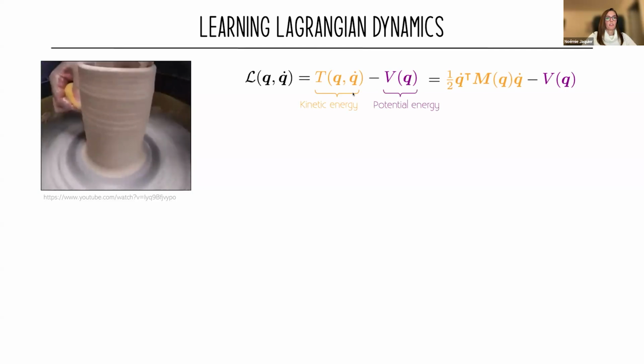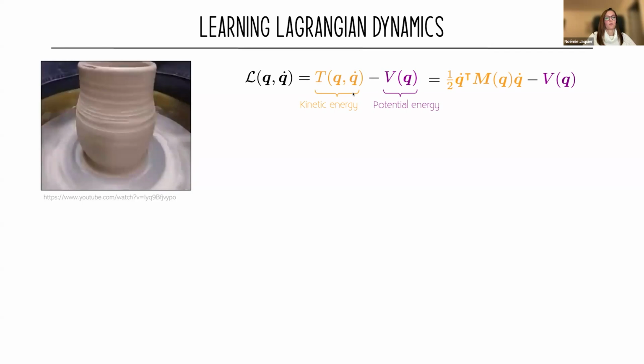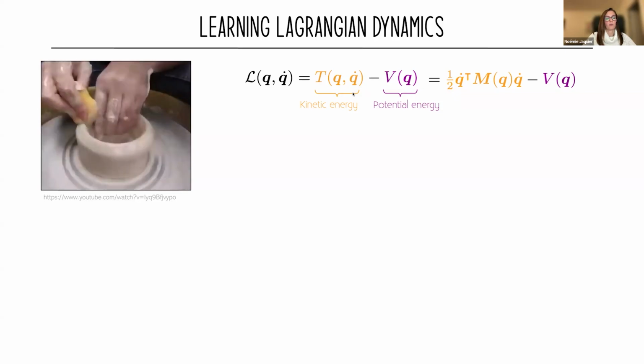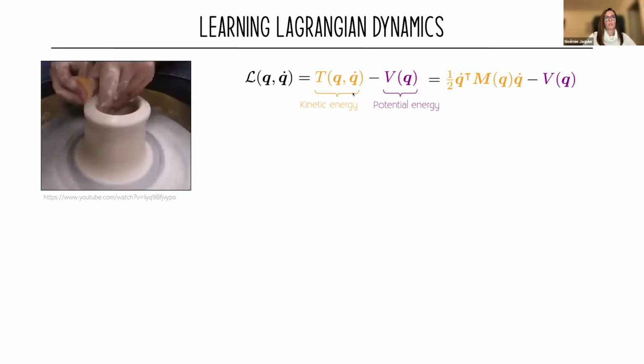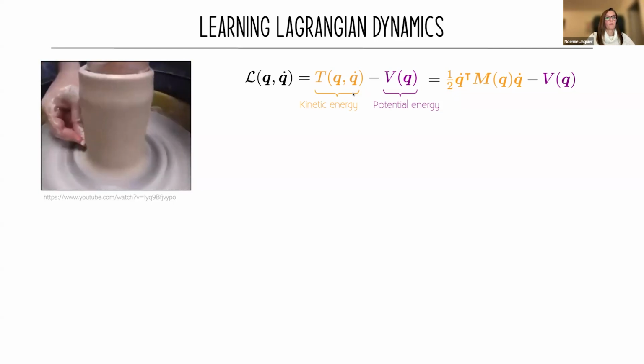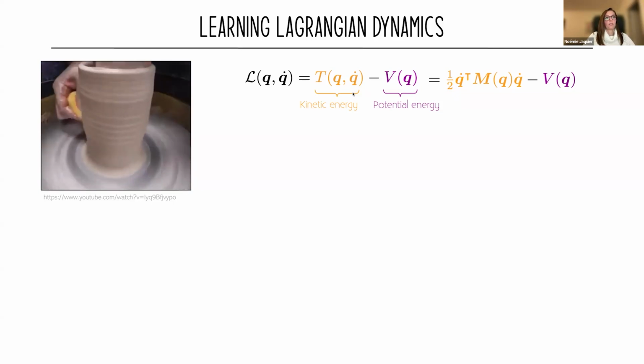The setup here changes compared to what I presented before, in the sense that when we considered the motion of the human body or the motion of the robot, we assumed that we knew the dynamic parameters. We knew what the mass inertia matrix was, we knew what the potential energy was, and then we were working with that. Now, in that case, you can assume that you see an object for the first time, and you don't know how this object reacts.